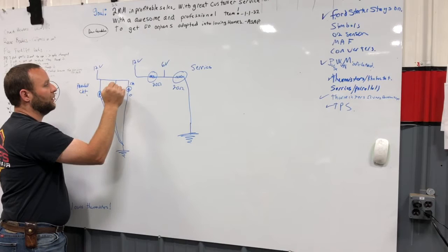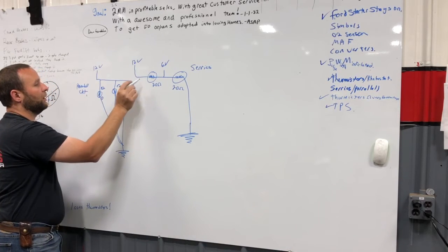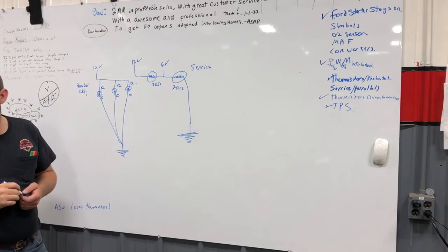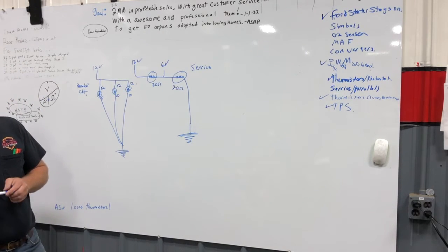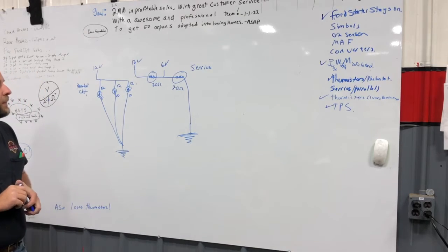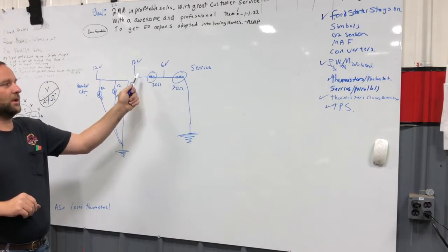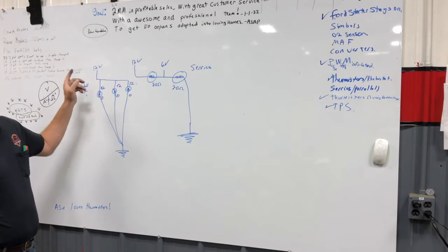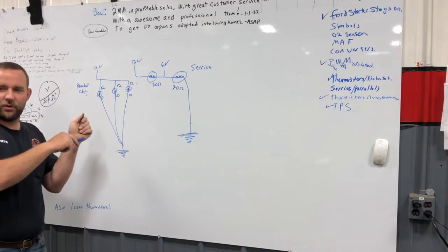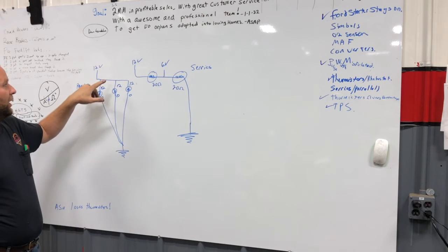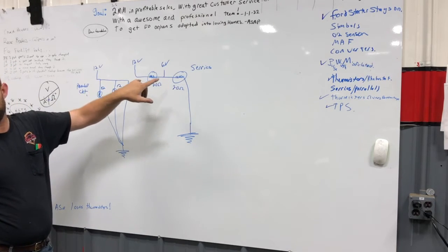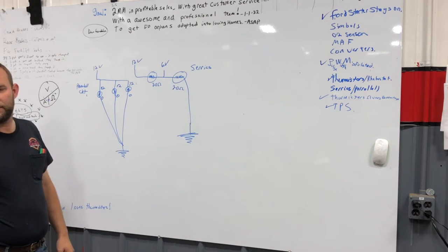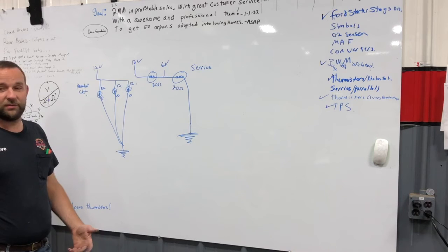That's how cars are wired, and most everything is parallel, except for fuses. In all reality, fuses are the only thing on series. GM used this system here. They would run cooling fans. They'd have 2 cooling fans, and a bunch of relays, and you'd run them in certain orders. They would go from a parallel circuit to a series circuit. This was the low speed, and this was the high speed. Seems a little more complicated than it needs to be. It's kind of complicated, but it worked reliably.